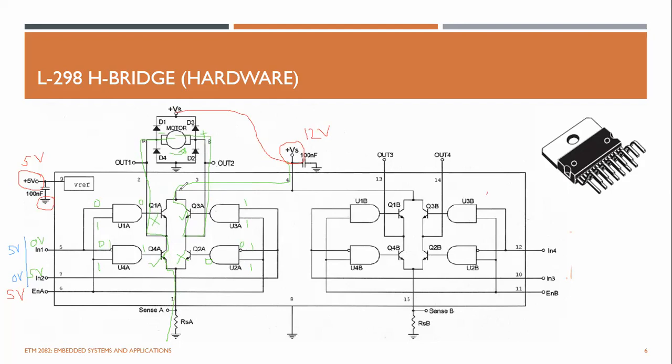Okay, so this is the simple way of changing the direction. Now if you want to change the speed, what can you do? In that case, assume you want forward rotation with the PWM signal. I want the forward clockwise direction, so I can just provide 5 volt here and 0 volt here. And for the enable, I can provide this PWM signal with different duty ratios, right?